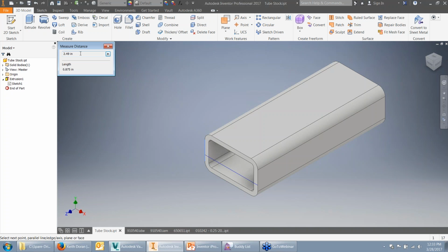So that way you can adjust your design to reflect the tolerances in case you need to look at a limits and fit situation or stack up situation. You've got a bunch of parts going together, and what happens if they're all made to max or all made to min or vice versa, a mixture? What happens to that stack up? Does it still fit together like it should? So the model is actually going to reflect that not only in the piece part, but also in the assembly and also in the drawing.